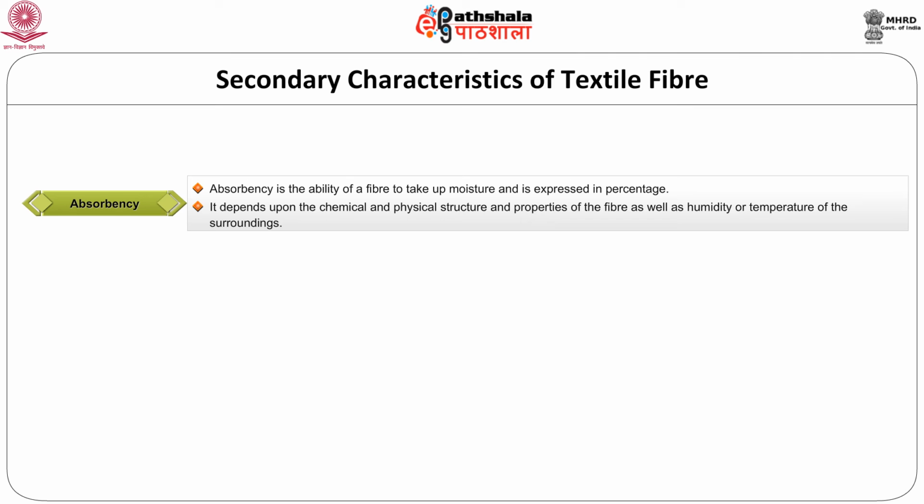The fabrics made from high regain fibers are considered as comfortable fabrics because of their absorption-desorption properties. Absorbency is very much required for apparel fabrics as the sweat needs to be absorbed into the fabric to keep the wearer dry. The moisture absorption in fibers affects its strength and dimensional, mechanical, electrical and frictional properties.